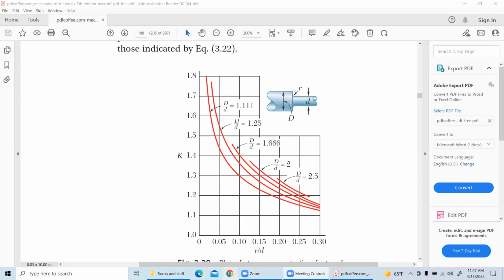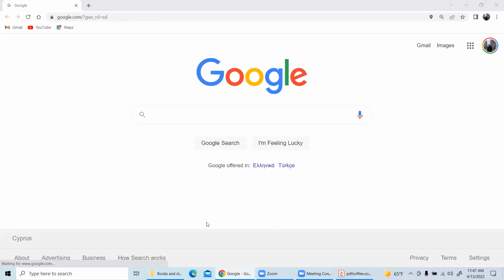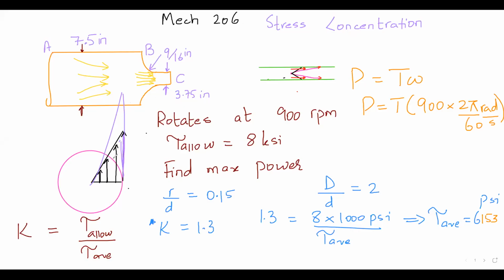Left and right, and we have arrived at this. In order for me to have this relation of the average shear stress work perfectly in this region, I have to use a K value. Because only the K value will tell me that actually here you have a non-linear profile, let's say like this, something exponential. Non-linear. And now the K value will make sure that this chunk is within the limit. So K value is like a safety factor, right? Let me put it in very simple terms.